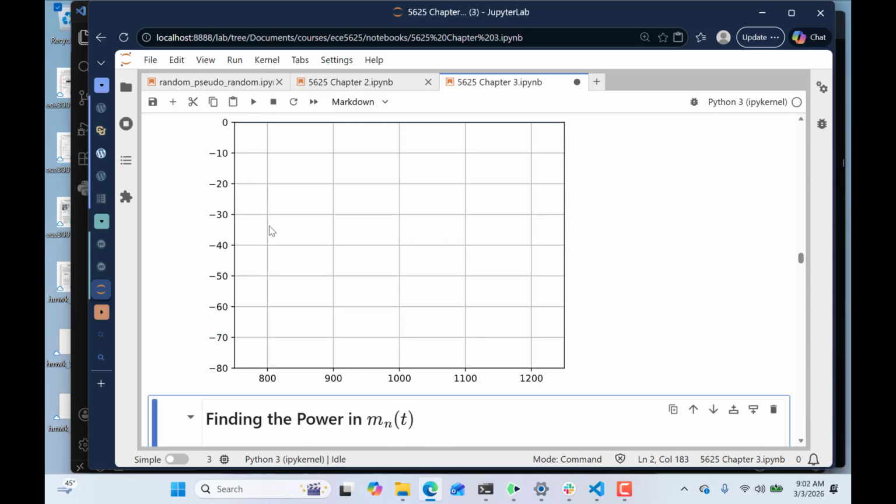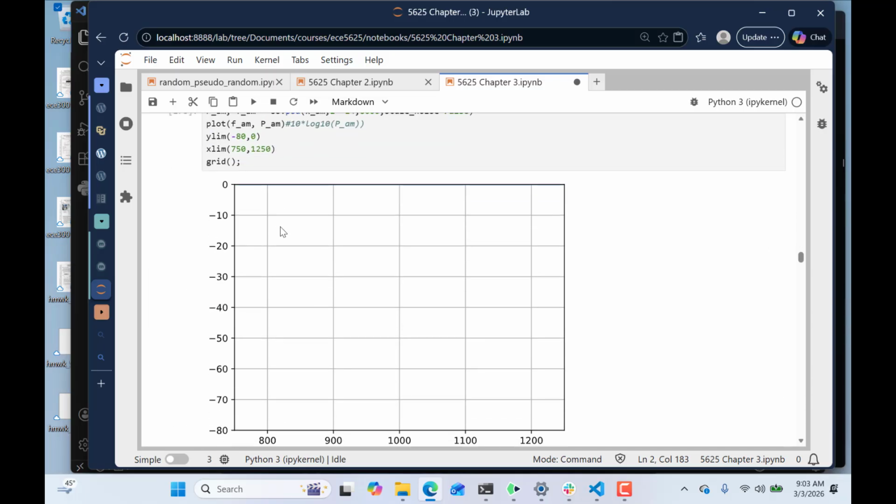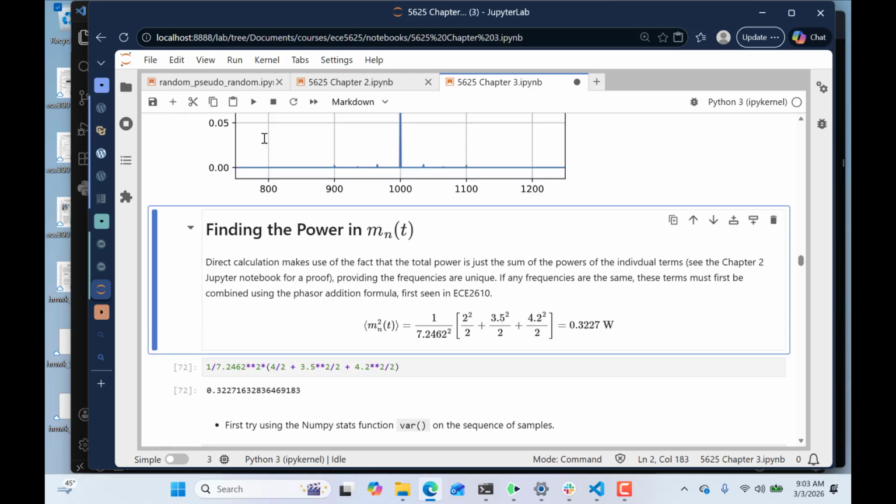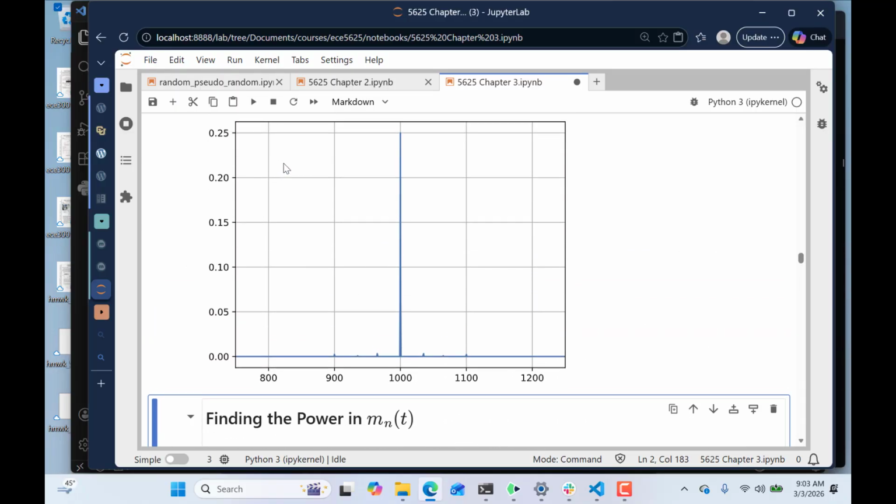Yeah. It's gone, right? Now, what I have to do is comment this line out temporarily, and just see where it's at. So I'm not even going to bother to rescale it because this is actually pretty good value. So now you can see at 50% modulation, the little sidebands are way down. The carrier is just like poking. It's like a tent pole, right?